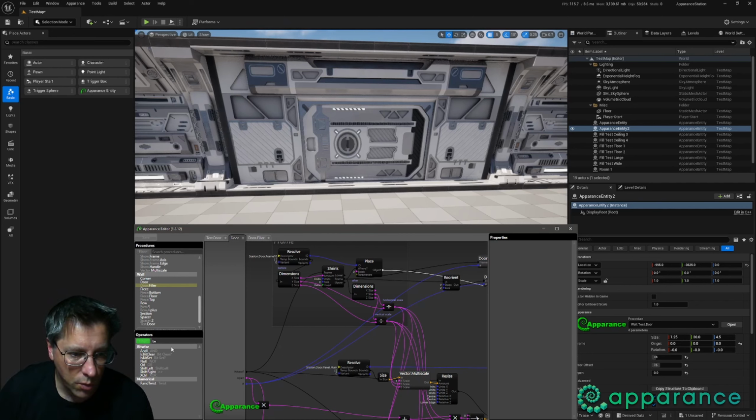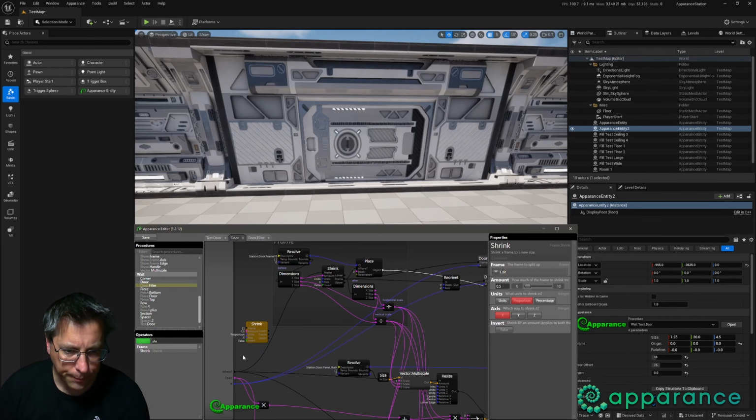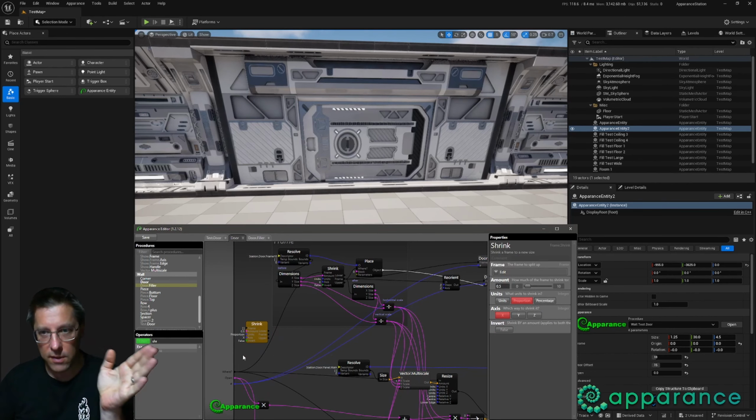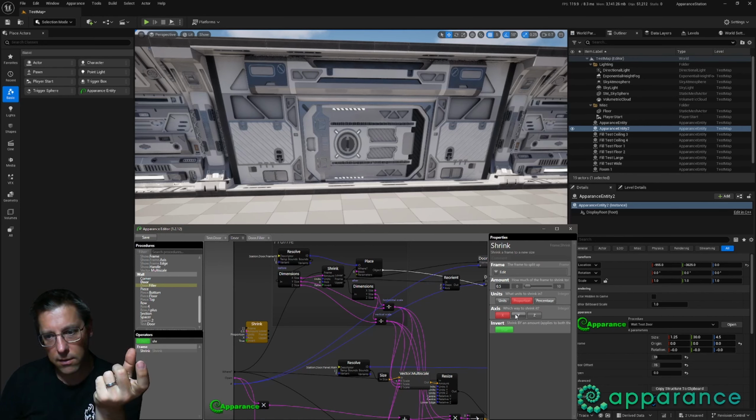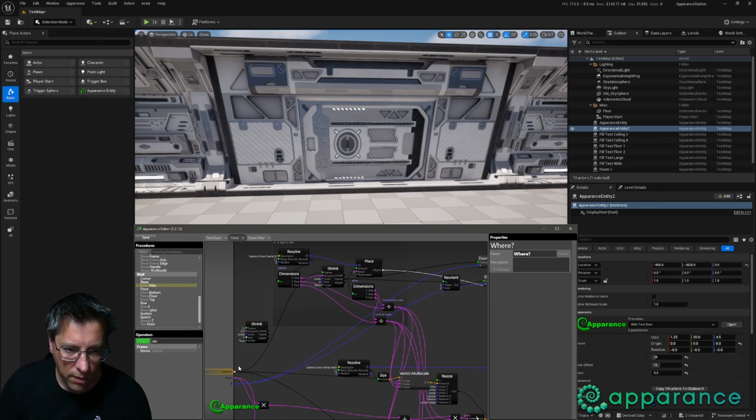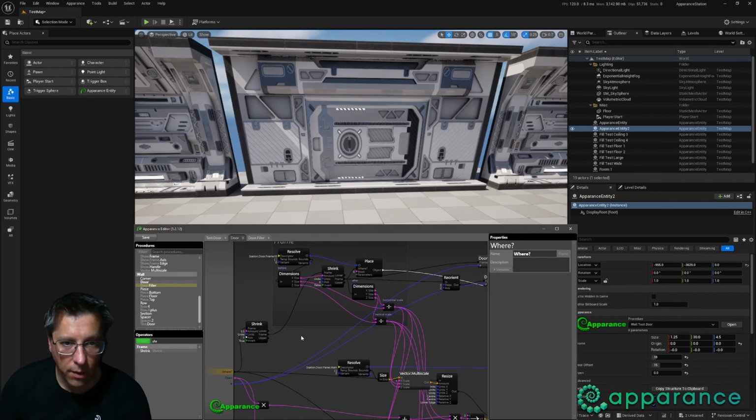frame, which we can do using a trick of the shrink operator. So the shrink, you specify the size you want to shrink to, but if you tick this box at the bottom here, it will shrink by that amount. And if X is the thickness, Z is the height, Y will be how far along, and we're going to do some units. So let's try doing that. Okay, so I've shrunk it by a whole load.